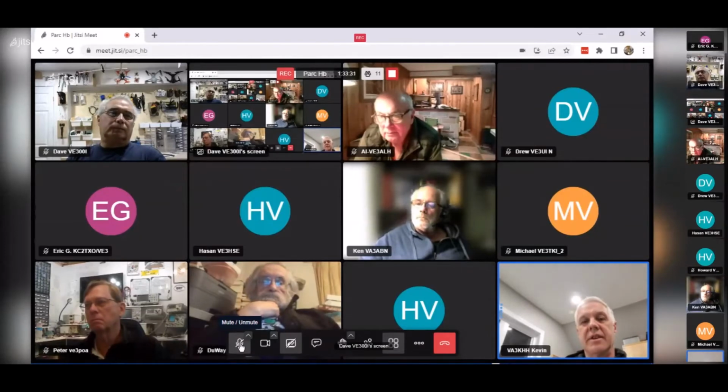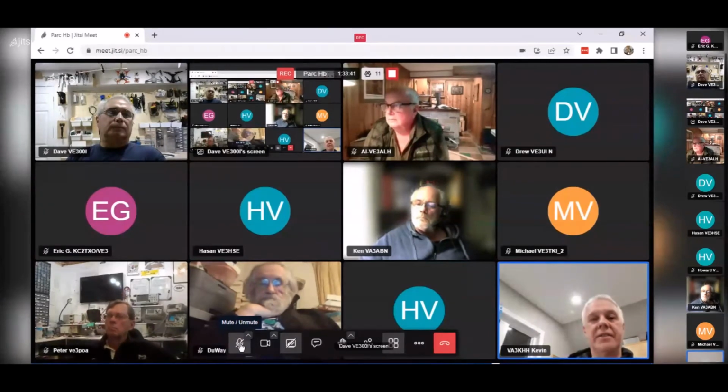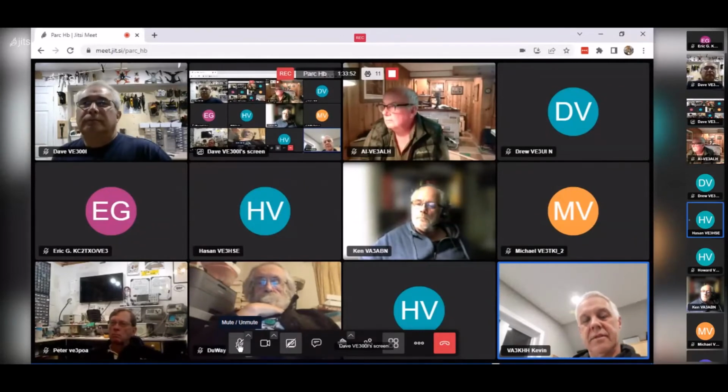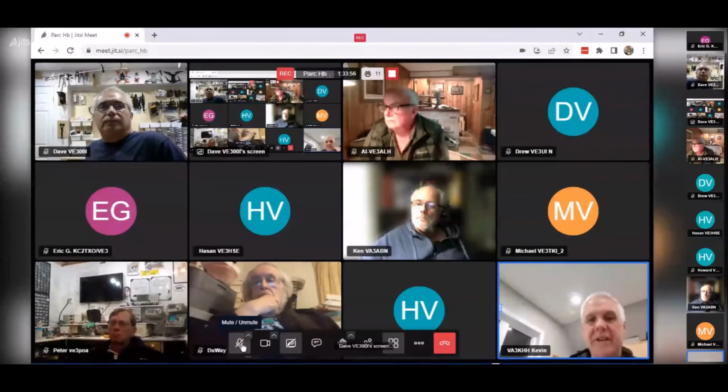Whereas in a servo, if I ask it to go from 0 to, like, 1,000 RPM in half a second or something, it'll put like 300% torque in there right up to the point where it gets up to the speed set point, right? And then it'll back right off. Did you have to do voltage control? Yeah, servos have a linear voltage characteristic on the motor, right?